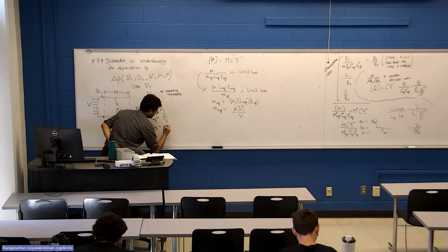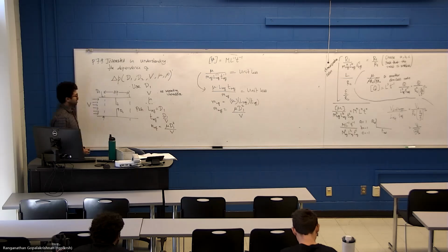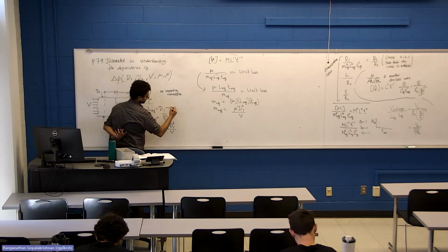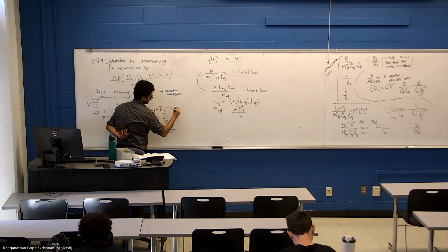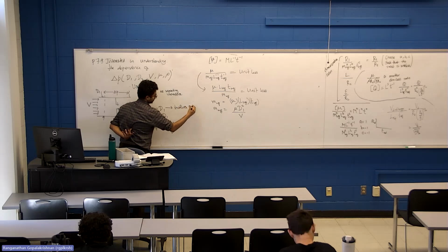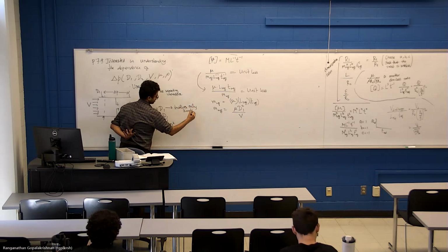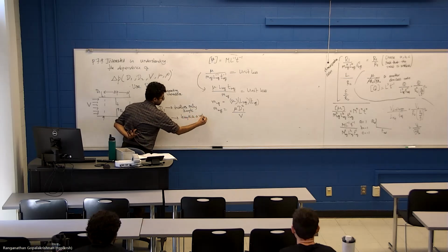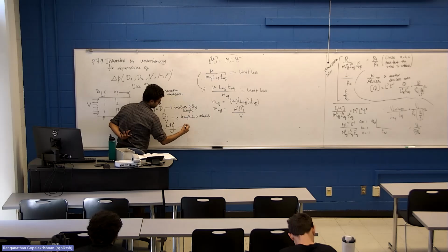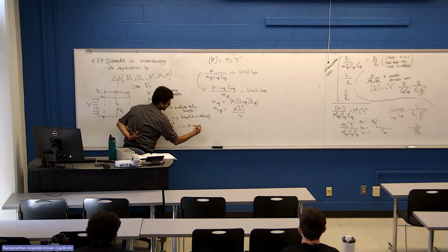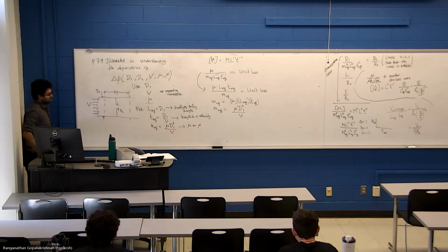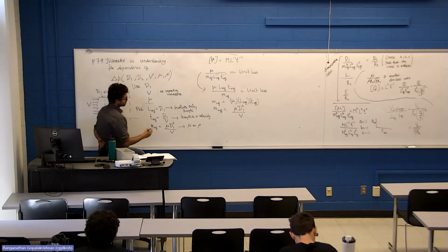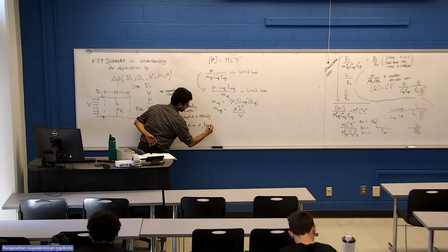This must be M ref. So this is mu D1 squared over V. Look at this. The reference length involves only length. The reference time typically involves length and a velocity. And the reference mass typically involves either viscosity or density, and a length and velocity.